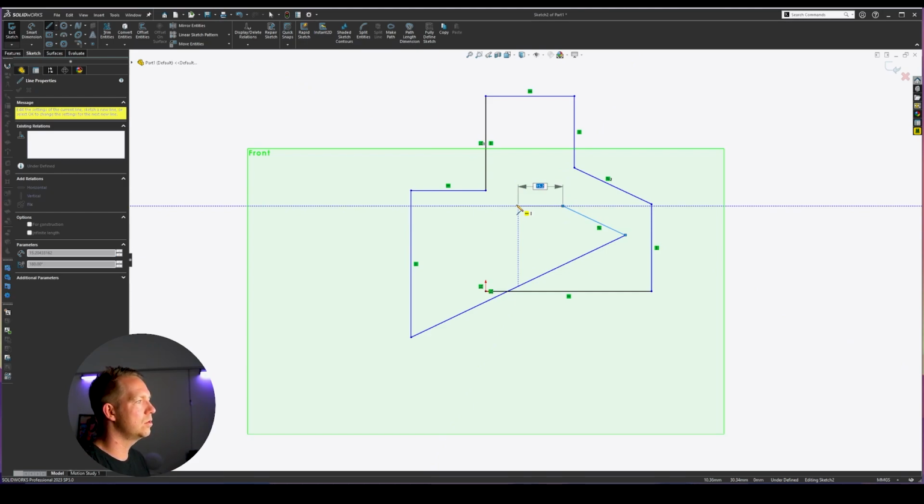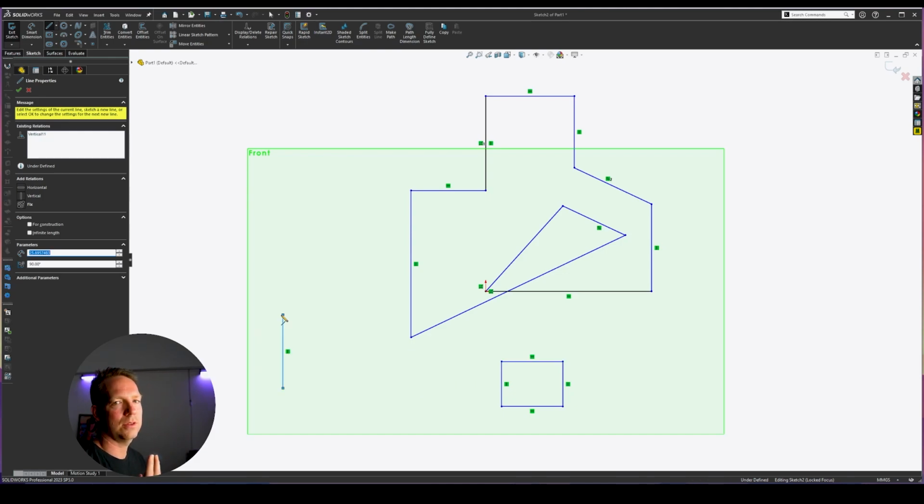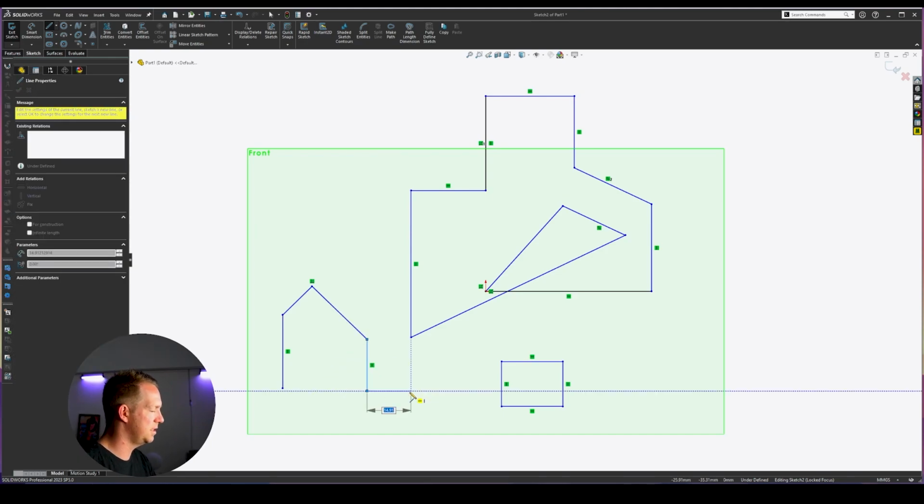All right, I'm going to finish my sketch by going back to the very first point of the origin. Now, whenever you draw a sketch, and here I'm just doing a new shape, and you come back to the start point, that will automatically end that sketch segment. The other two ways to end a sketch segment that I'd like you to know is by double clicking, okay? And then the other method is to press the escape key.